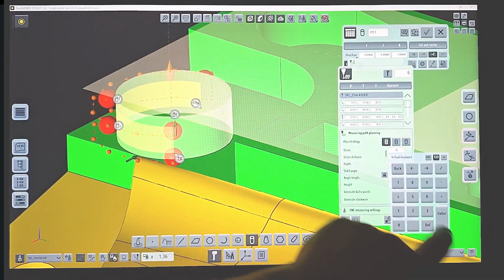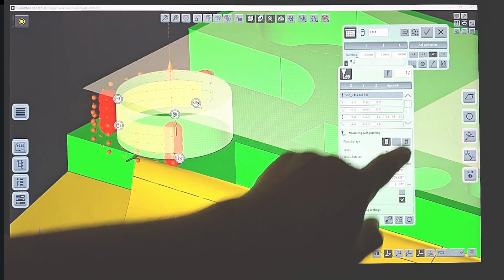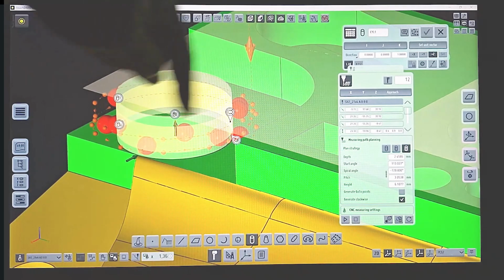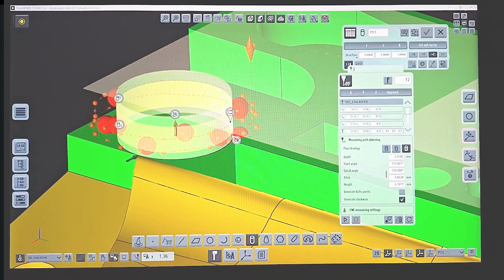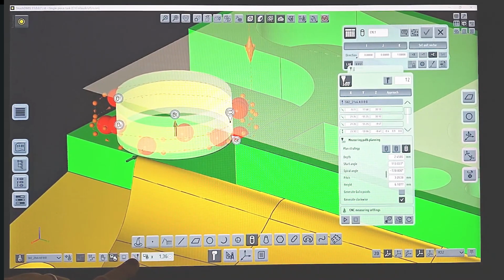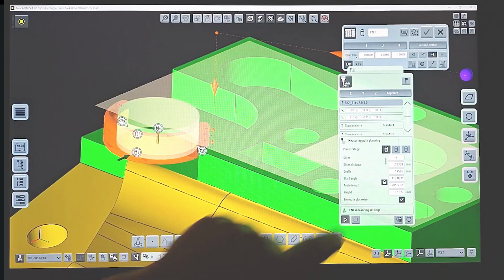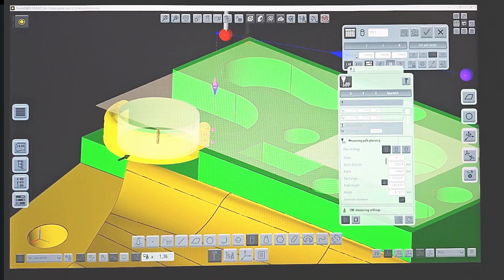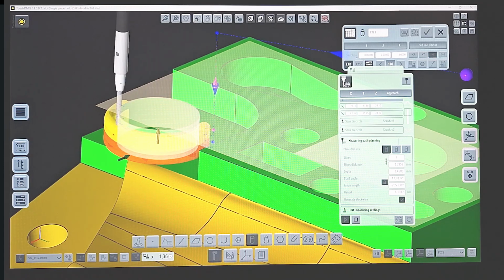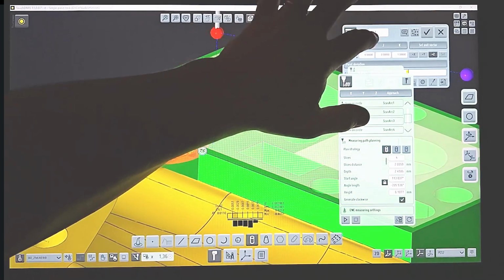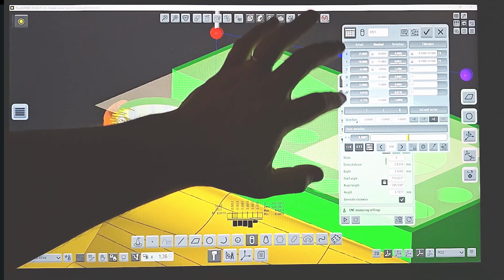For slices, for example, it can be done along the generatrix of the cylinder, or it can be done on a helical path. Interesting that in TouchDMIS you can easily switch to scan mode by tapping this button. So, in this way the machine will perform in continuous scanning mode. We apply the tolerance and we have the report.